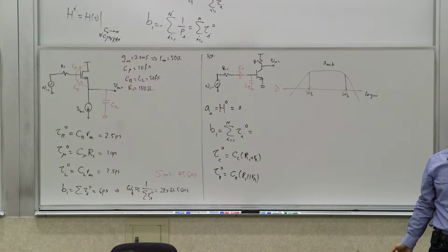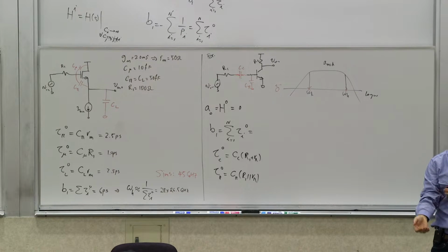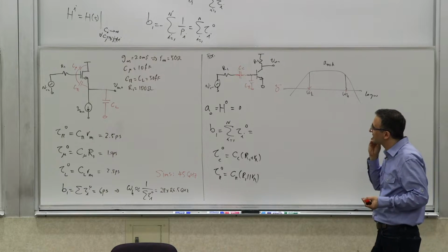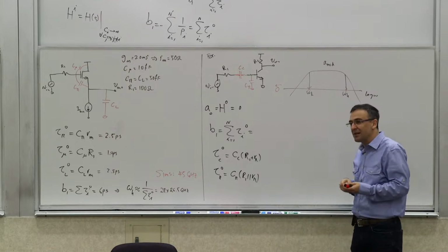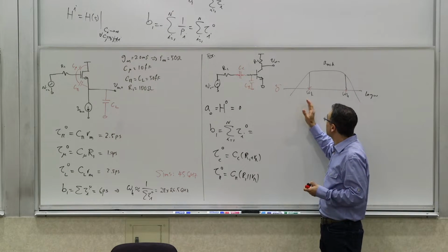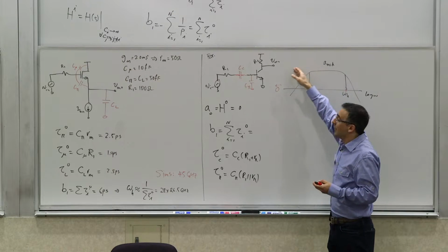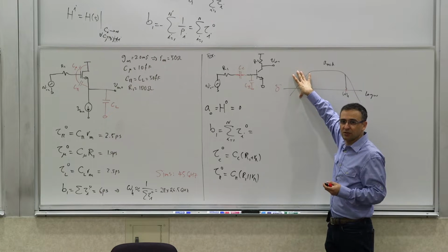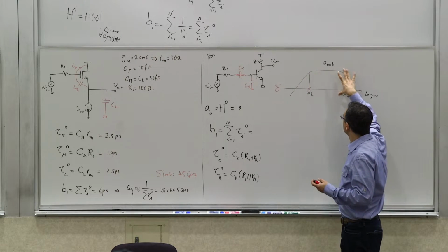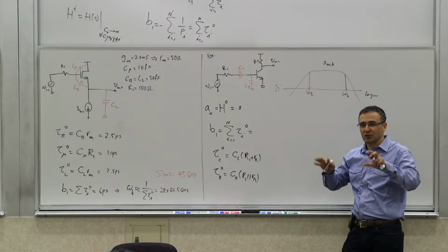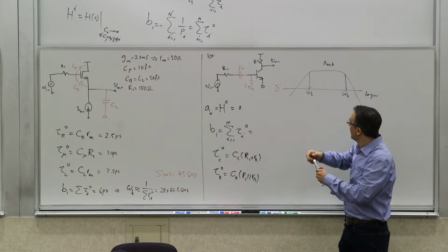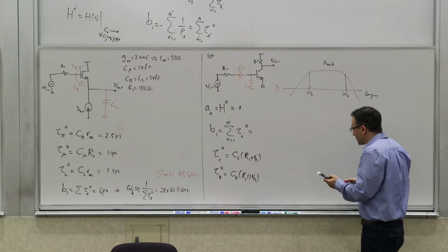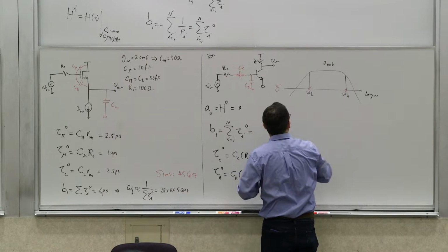Well, you could say, okay, well, let's go calculate B2. We could do that. But there is a better way to think about it. There's a simpler way to think about it. You remember in the beginning we said that any transfer function could be divided into a high pass and a low pass. These were the inverse poles and inverse zeros responsible for it. There was a mid-range, so we wrote the transfer function as 2 parts, right? So that's the left part. Now, we could also look at only one part. So we said, for example, let me just rewrite that to refresh your memory.